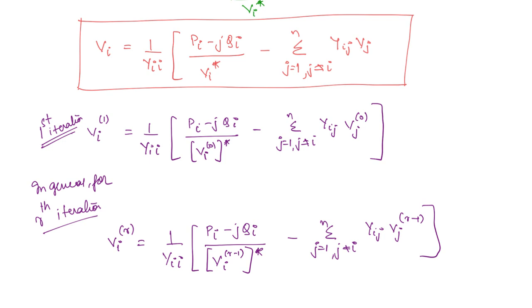Here there is one more thing you can do to speed up the iterations. So if you understand, well and good. If it is getting confused, don't worry, you don't have to remember it. Here you are writing the r minus 1th iteration, right? Now let us say you are finding the voltages for buses 2 to p plus 1, right, for the PQ buses. Now let's say the voltage at bus 2 you have already found out.